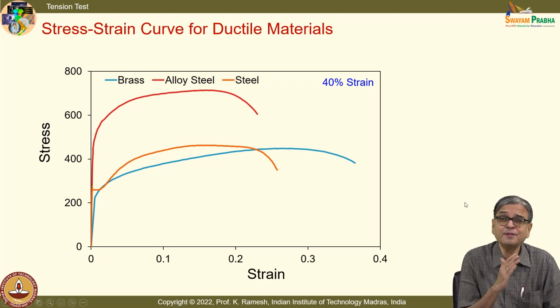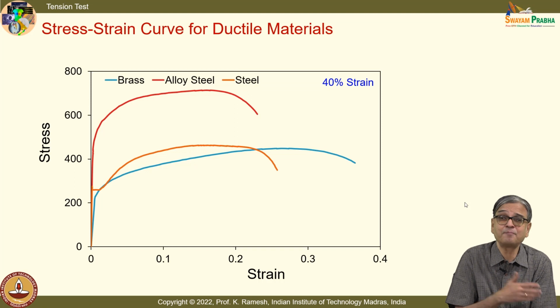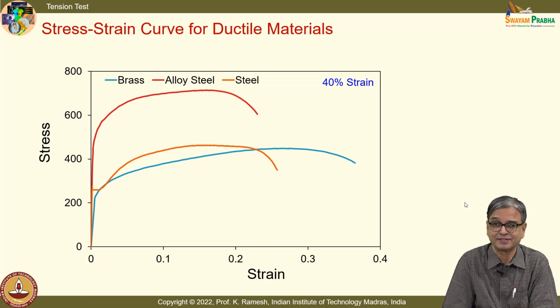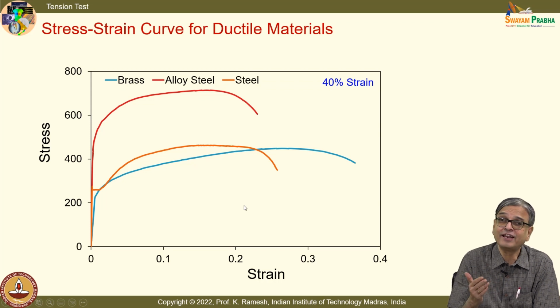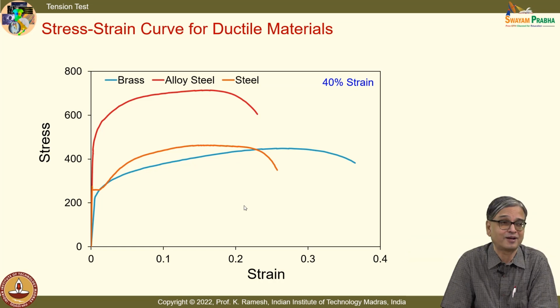But there is another important observation, let me see whether anybody makes it, which is important from your strength of materials point of view. Because why do you do alloying? You want to improve the material characteristics. By alloying, you have been able to improve what? You have been able to improve the yield strength. Can you do anything with Young's modulus? What does the graph say? Does the graph give you some clue on what happens to Young's modulus by alloying?